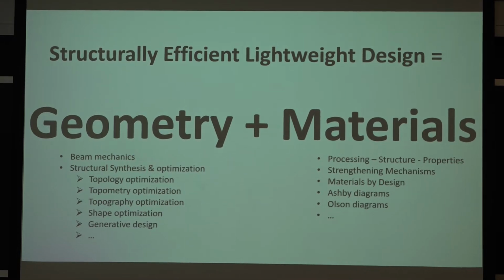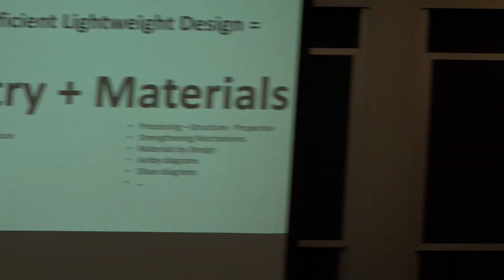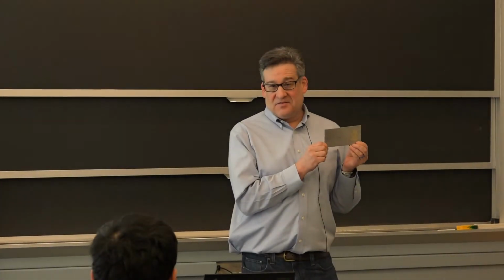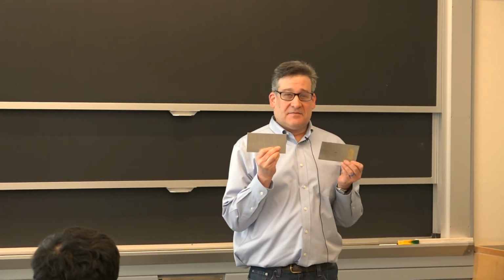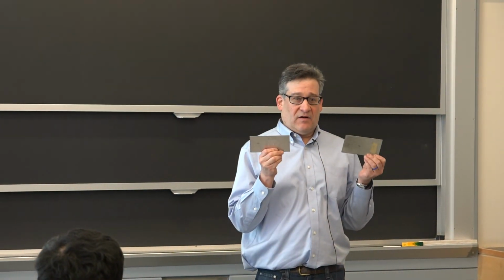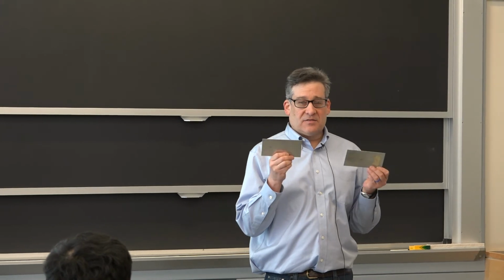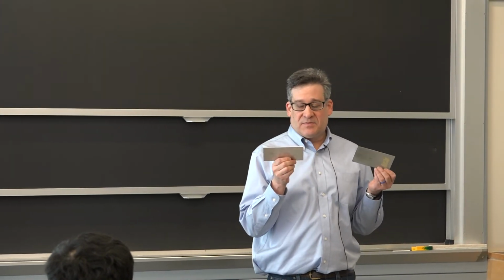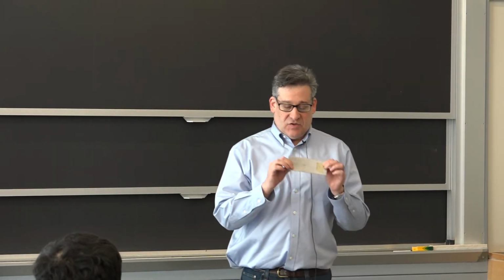And then we have a piece of aluminum that has Nextel or aluminum oxide fibers embedded in it. And this is a great example of where a material has been designed to be stiffer than its cousin. Okay, so this is aluminum. These are both made out of roughly the same alloy. It wouldn't matter because all aluminum has about the same stiffness anyway, same Young's modulus. But this is like 2 to 3 times stiffer.